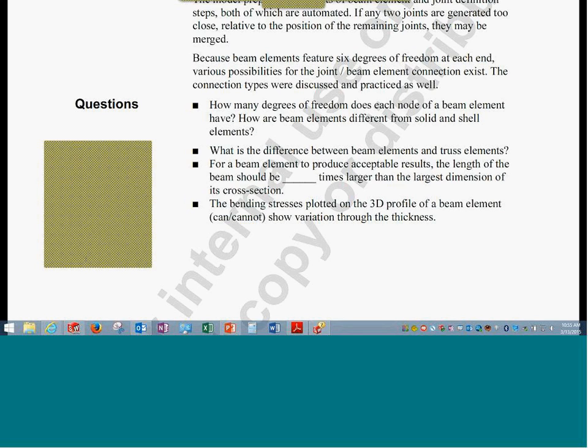The same rationale is what we were speaking of in terms of shell elements, that is, in terms of thicknesses. It does not make any sense to represent a geometry which is not 3 times its cross-sectional dimension as a beam. But it could be a case wherein there is a huge number of beams and one small part here and there that you do not worry about. It's okay, we are using it only for connections. Then you can use the option available in this software.